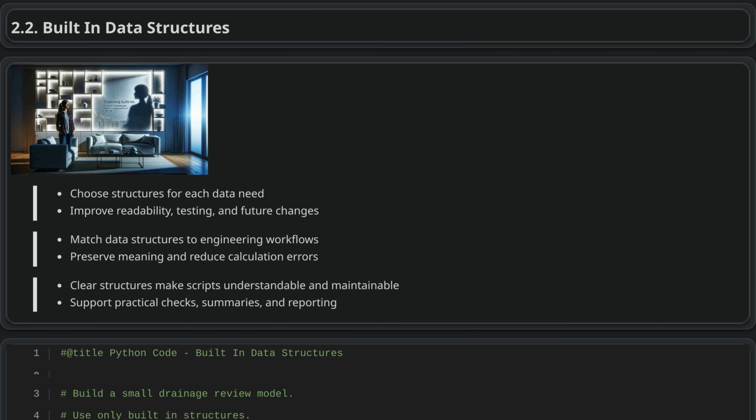Script review. Technical validation. Technical validation checks that an engineering script produces accurate, appropriate results, not just that it runs without errors. In civil engineering, this means confirming that inputs, units, coordinates, elevations, and project conditions are handled correctly. A script should be tested against simple hand calculations or other transparent checks before being trusted on larger work. Validation begins by defining the script's purpose, expected data, reasonable results, and how those results can be verified.